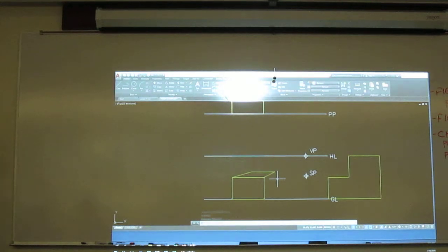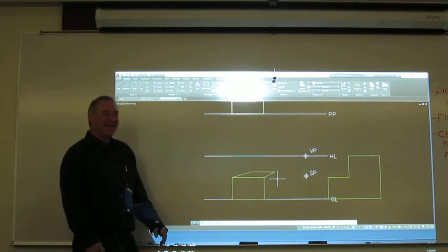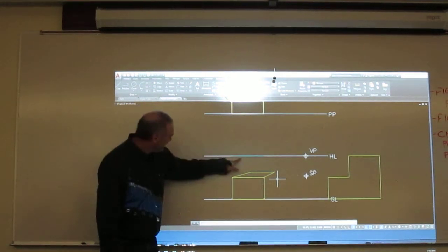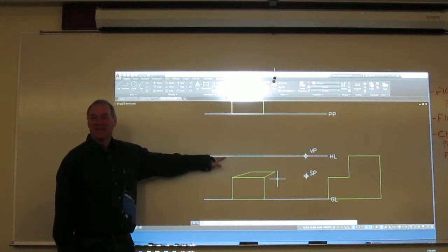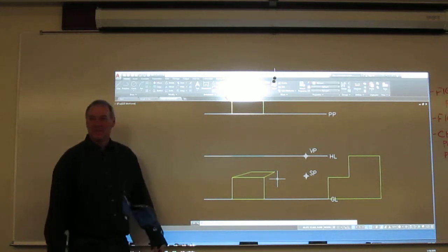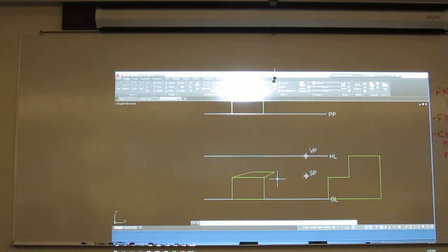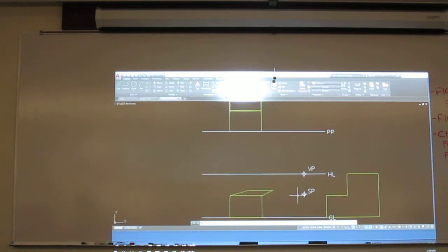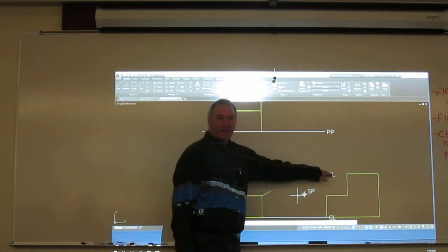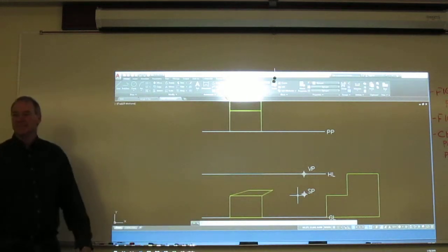So we should have slid the horizon line, I apologize for that. Because we did a 4 offset, this guy's 4. Do you see that cyan piece right there? Okay, that is true size. Again, raise your hand if you're not sure what we're doing and you need help. And it doesn't have to be on the horizon line, it can be anywhere in between. My height right here just lines up right with it. But if yours wasn't, that's why I said that, but it's okay.